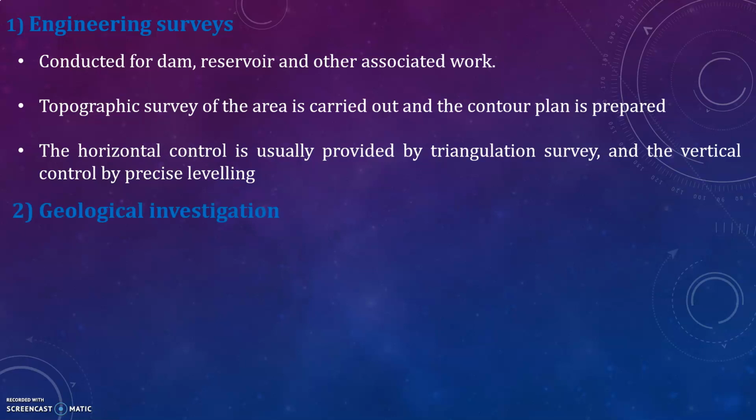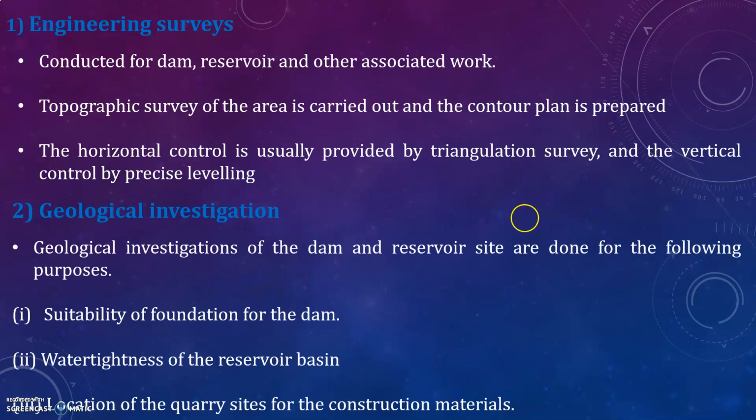The second one is geological investigation. Geological investigations of the dam and reservoir site are done for the following purposes. The first one is the suitability of foundation for the dam, water tightness of the reservoir basin, and location of quarry sites for the construction materials.